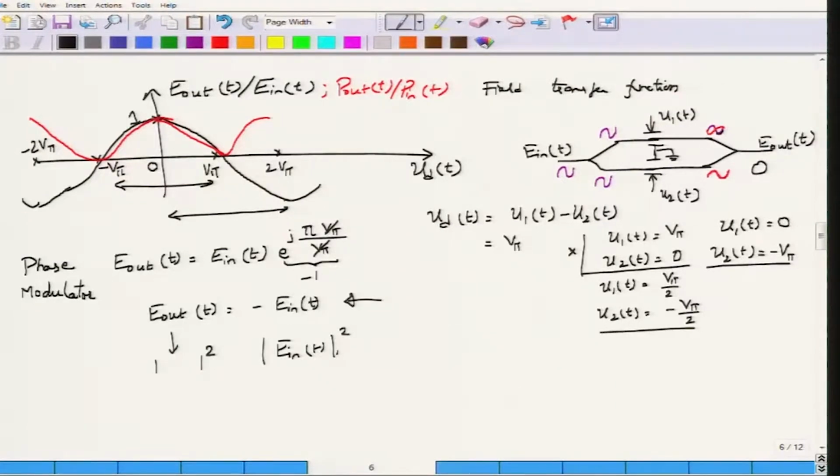So, we have now discussed two modulators, one is the phase modulator and the other is the Mach-Zehnder modulator. Let us try to put them into use to see how we can modulate the phase of the light signal and to realize the phase modulation or amplitude modulation. Since it is amplitude modulation that we are normally familiar with, let us begin with a slightly complicated example of modulation, that is Mach-Zehnder modulation.